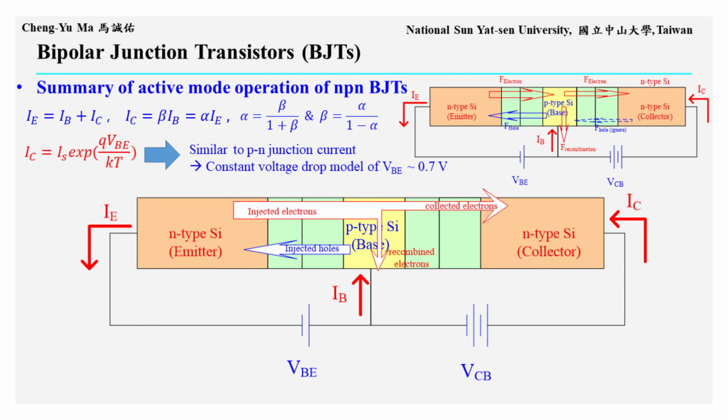The main emitter and collector currents come from the forward-biased BE junction. When the device operates at a relatively high conduction current, the BE junction forward voltage can be approximated by the constant voltage drop model, so VBE is usually taken as about 0.7 volts. This approximation makes DC circuit analysis much faster.